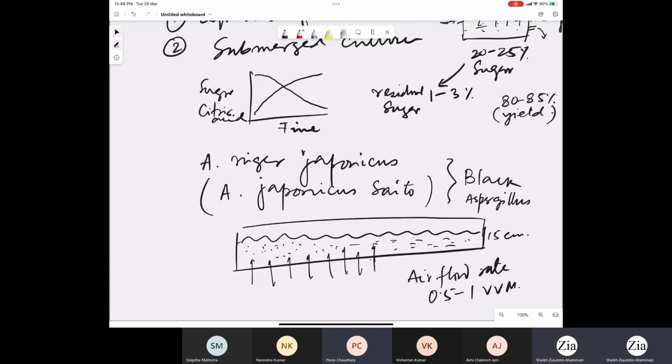Here also you have the option to use different kinds of vessels. As we are handling very low pH solution, you have to make sure the vessel does not interact with the liquid and does not introduce any iron or copper ions. Glass-lined vessel is okay, but you should not have blue glass-lined vessel, because blue glass will create problems with cobalt and nickel.